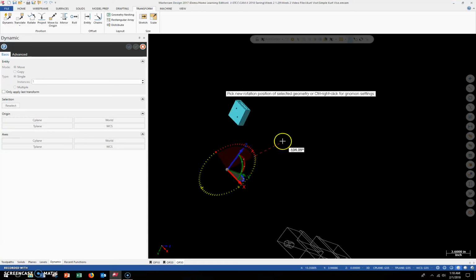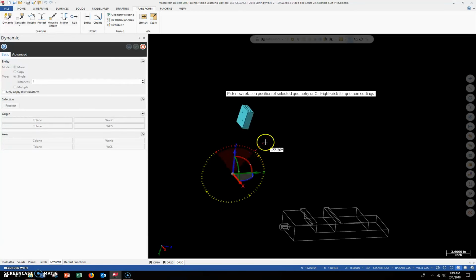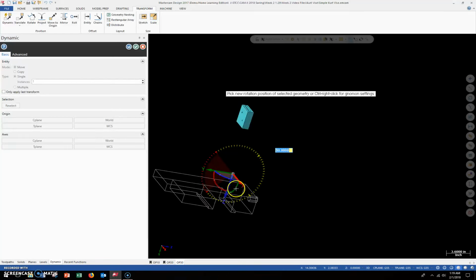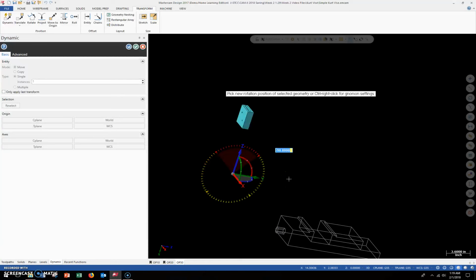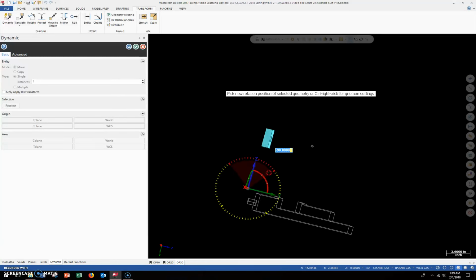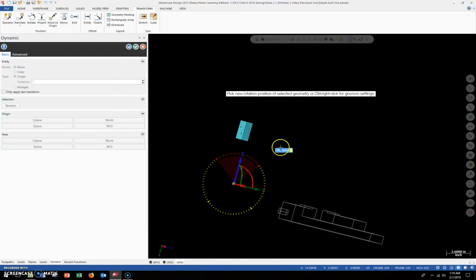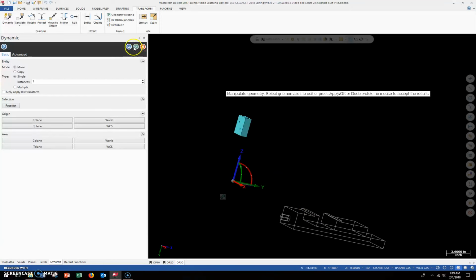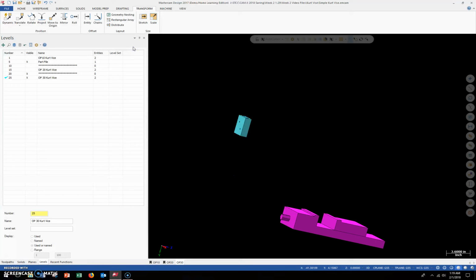That looks pretty good. All right, that's the direction we want to go in. It's a 90-degree move. Okay. In this case, you'll notice that that's the wrong direction, right? We want to go the other way, 90 degrees. So in this case, we want to change that to negative 90. Now we have the right orientation. You see how that works? So again, negative is used for directional use only. I like that. I'm going to hit enter one more time, and then I'm going to click OK.